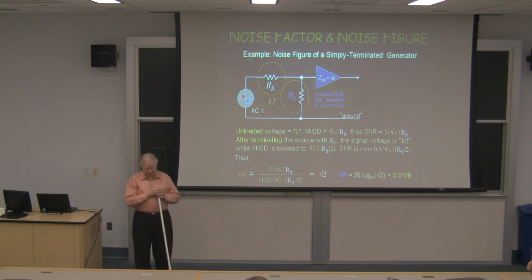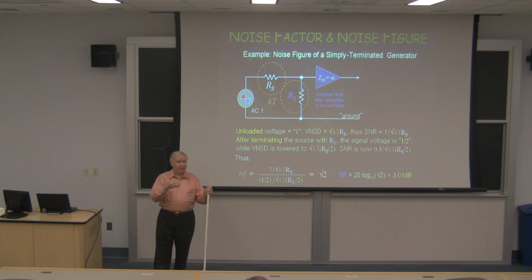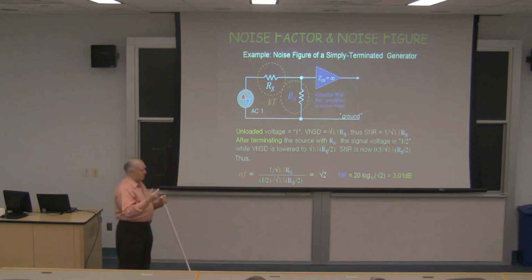Another thing that's worth mentioning too is that bit error rate, as a measure of one of the implications of noise, is going to erode. Well, the ratio between the bit error rate and the noise figure is around about 10 at 12 dBs. It's a rather complicated curve, but if the noise figure is about 12 dB and you can get it down to 11 dB, it will be 10 times better in terms of bit error rate. So it's a big deal, particularly since every communication channel these days is doing it.